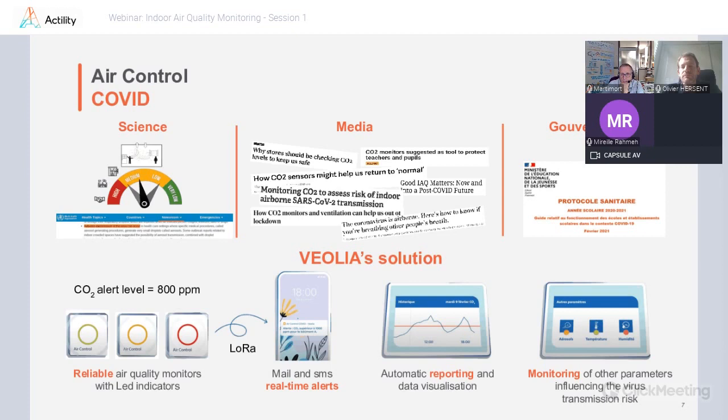Concerning the calibration of VOC and CO2 sensors, as we are a client for the sensor manufacturers, what we ask for is a pre-calibrated device, calibrated before we install it, and without drift over time. For the CO2, there is an auto calibration process that is based on the background concentration, the minimum concentration of the place. But I will let Olivier also answer this question about the calibration, because they already do that for their devices.